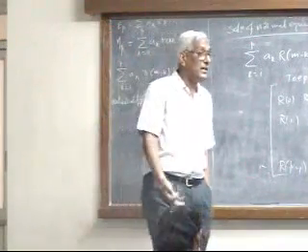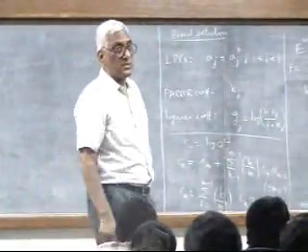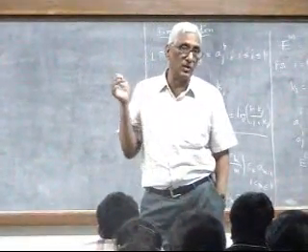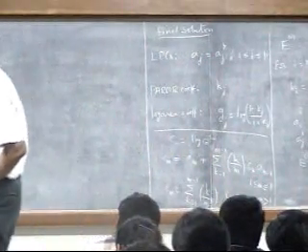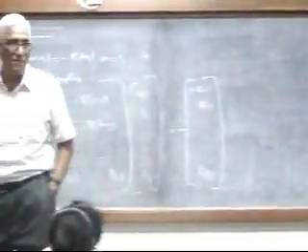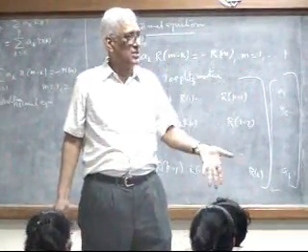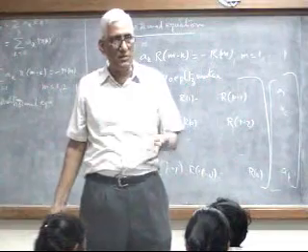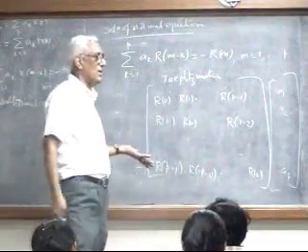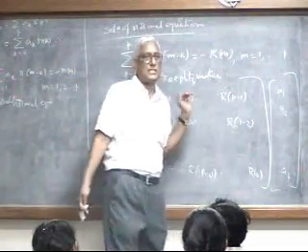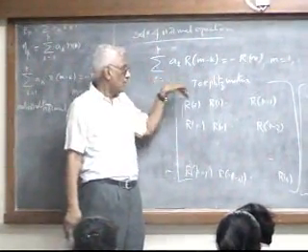And what does it mean in terms of speech? After all, speech, as I told you, it keeps coming every 10-20 milliseconds. You have to deal with the next one. So if you really want to compute this online or in real time, you have to worry about finishing all these computations. So reducing it by an order from p cubed to p squared is a big achievement, and that came out as a bonus in this case because of the special structure of this, and that is called the Toeplitz matrix structure, where the diagonals are the same.